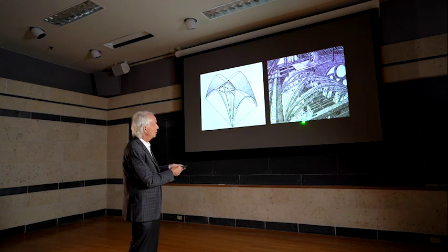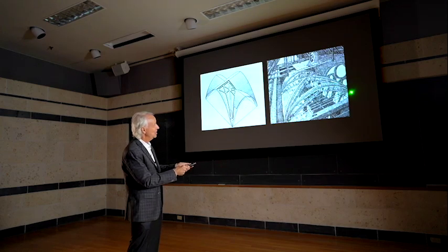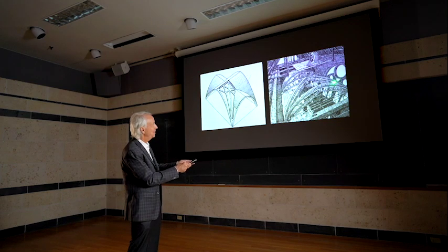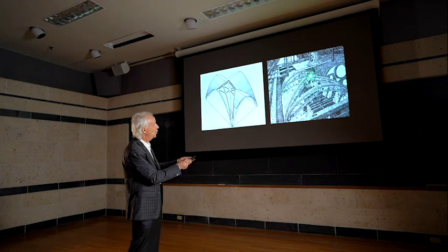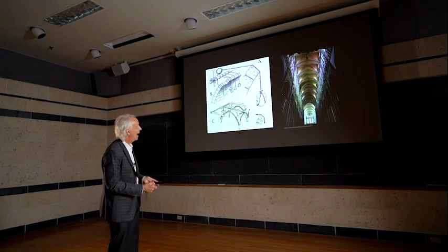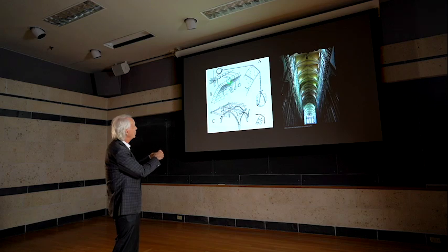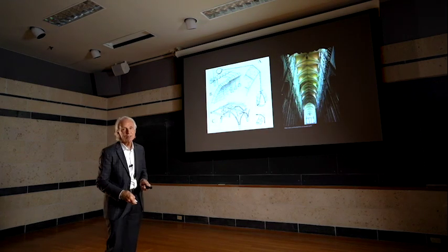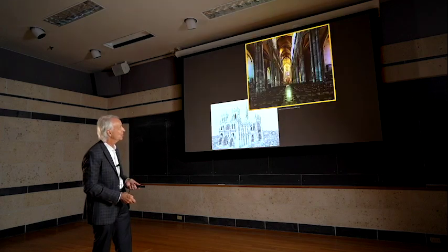And what they ended up doing was making this centering, like you see there, to make a web, not the whole vault, because that would have been too heavy, but just these linear pieces. And so first they make a web out of that, then they come back and they do infill by using what they called ropes and stones to simulate the load of the complete vault while the vault is incomplete. And they would put another stone in here, put that rope over here, hold it in place, and they just keep going and going until they complete all of the groin vaults at the top of the church.